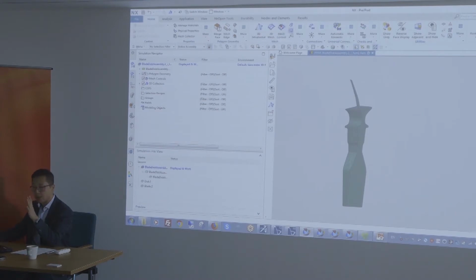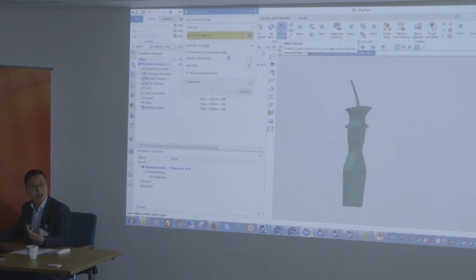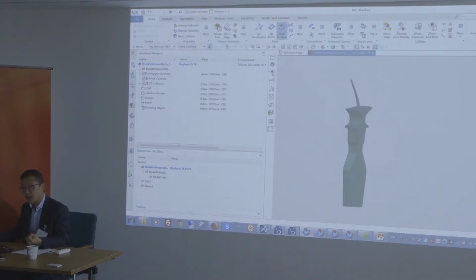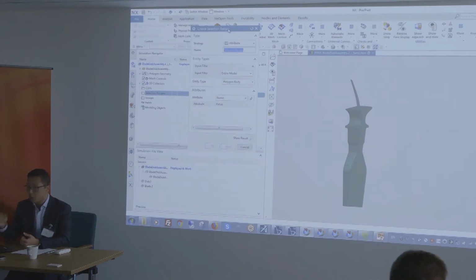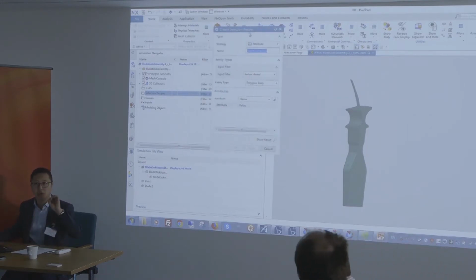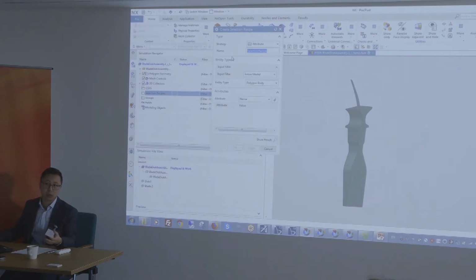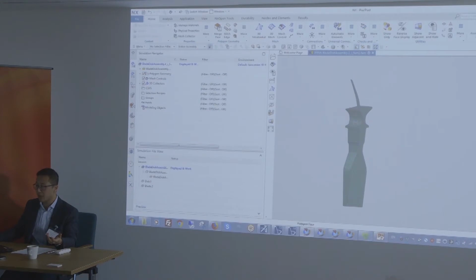So there's multiple kinds of elements. But if you want to be a bit more granular, and let's say you're doing some refinement, of course, all of the different tools and mesh controls are available to refine meshes in different areas of the model. And what's also nice is that these refinement tools can be tied to what we call selection recipes. So the same quantities I've used for topology optimization, right? So you can select or create meshes that point to features. Mesh all my parts of a certain color, or mesh all my parts with specific names in it.